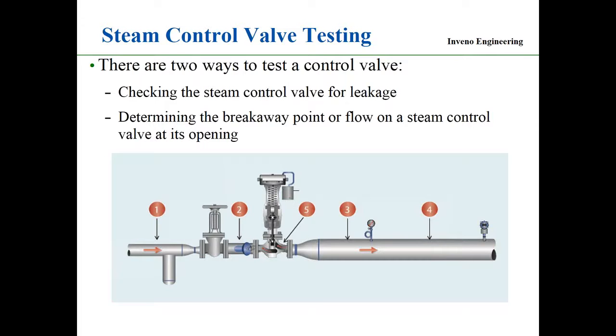Now, if you're just heating water to 80 degrees C, and you can take 5 plus or minus 5 degrees C fluctuation, it's not a problem. But we get into processes where you have to have plus or minus 0.5 degrees C. So this breakaway point inside this control valve becomes very, very important. Okay. So there's a couple things that we do on the control valves: setting up this control valve for the breakaway point and understanding the breakaway point in the valve, and that's setting up the control valve.